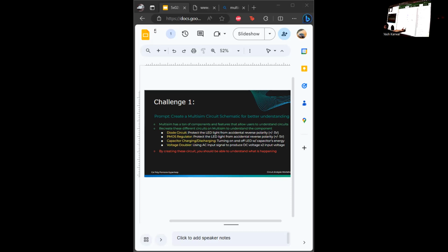But in a regular circuit, you don't specify where the ground is, essentially, right? In Multisim, you have to specify the location of the ground because that gives it a place to calculate other things. You put it here and it'll still work the same. But in Multisim, you just need this here. If you don't have this, your circuit won't work, because it doesn't know where to put 0 volts. Not only does this happen in Multisim, but in PSpice, you can't run it without ground. And I think in LTSpice, you can't either. So in every simulation, you have to.